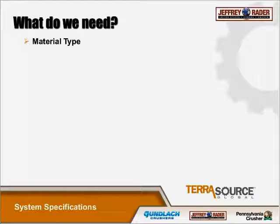So what do we need to be able to give you a pneumatic system? We need to know the material type. This determines several design factors, including initial velocity, which we'll go over in a minute. All these specifications are critical because they define a unique system. If anything's changed, the system will not work properly. We would need to know about it so we can make necessary upgrades or changes to the system. The rate, we don't want to guess on capacity. If you overestimate, you're going to be wasting horsepower. If you underestimate, it's not going to convey.